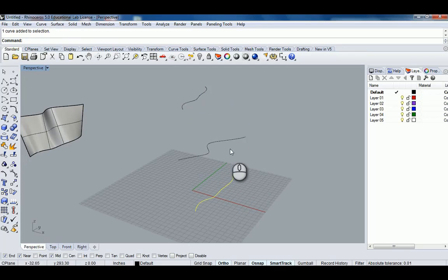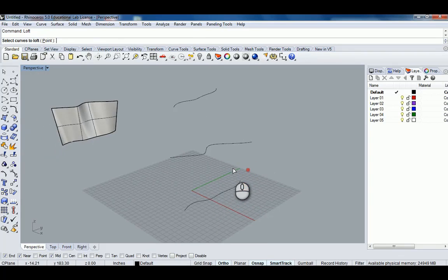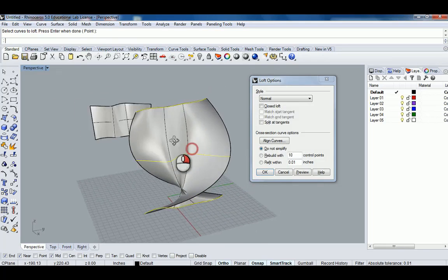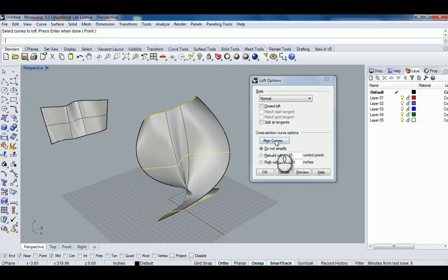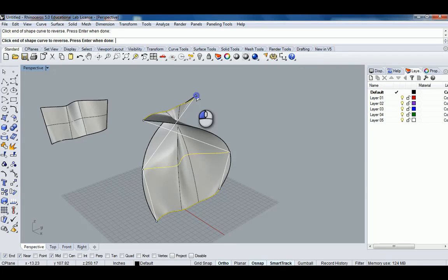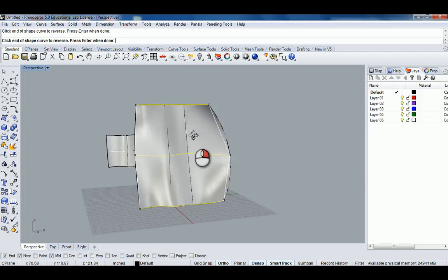So now if I type the loft command, and this is important, the order of the loft curve selection is important. So I typed loft. I've now chosen 1, 2, 3. It's also twisting these. So again, I have to go into my align tool and just simply reorient both of those until they're all lined up.